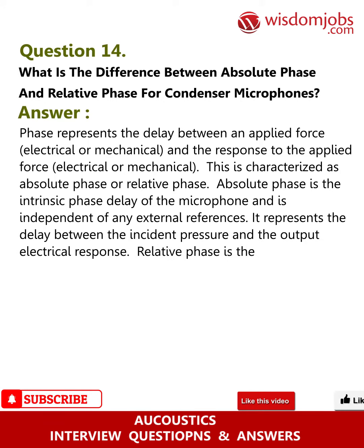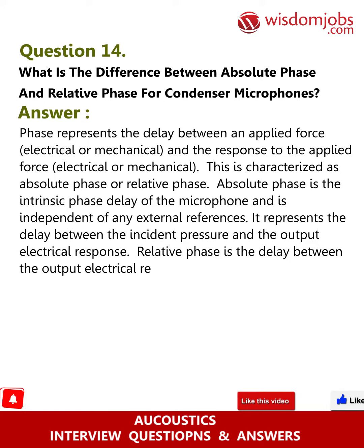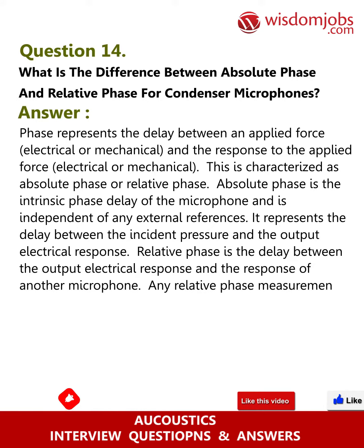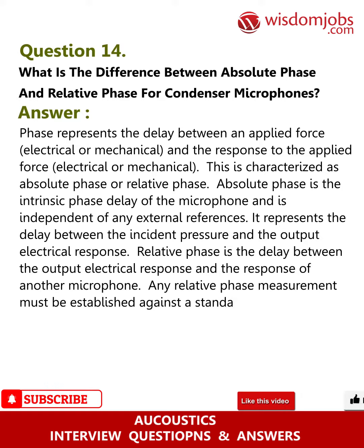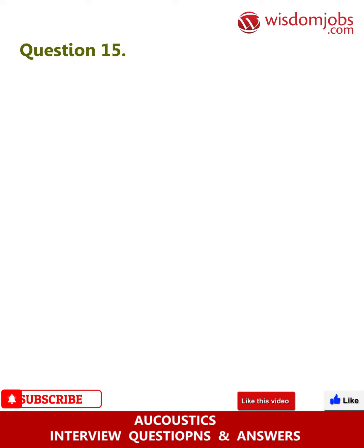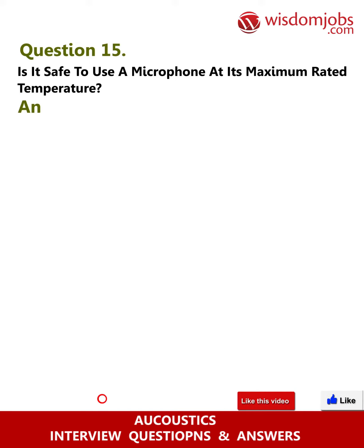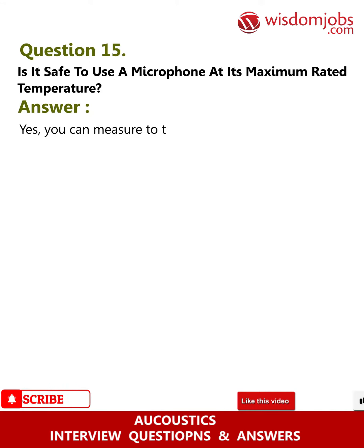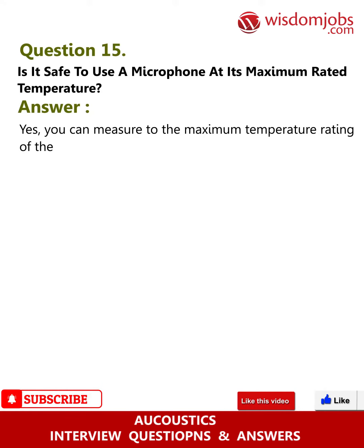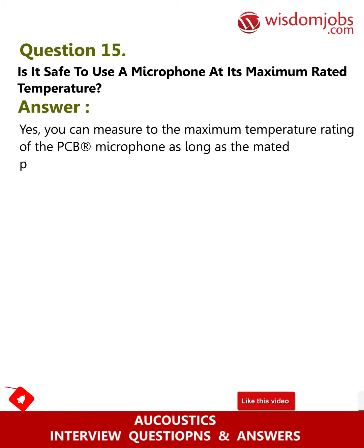Relative phase is the delay between the output electrical response and the response of another microphone. Any relative phase measurement must be established against a standard. Question 15. Is it safe to use a microphone at its maximum rated temperature? Answer. Yes, you can measure to the maximum temperature rating of the PCB microphone as long as the mated preamplifier is rated to at least that temperature.